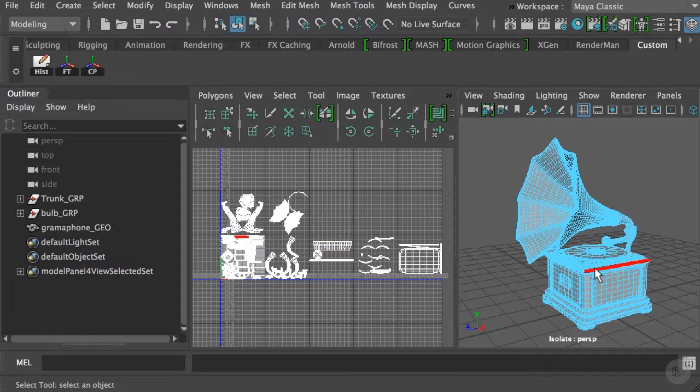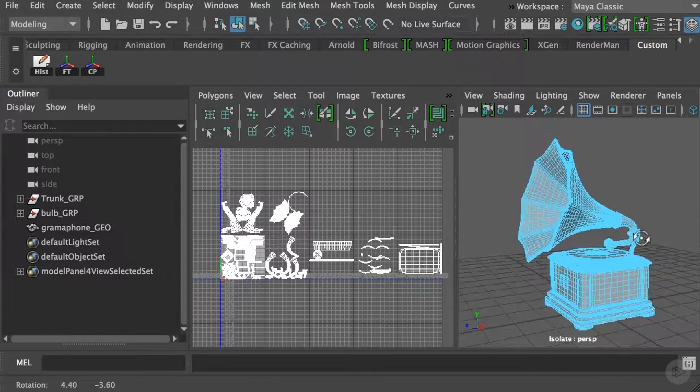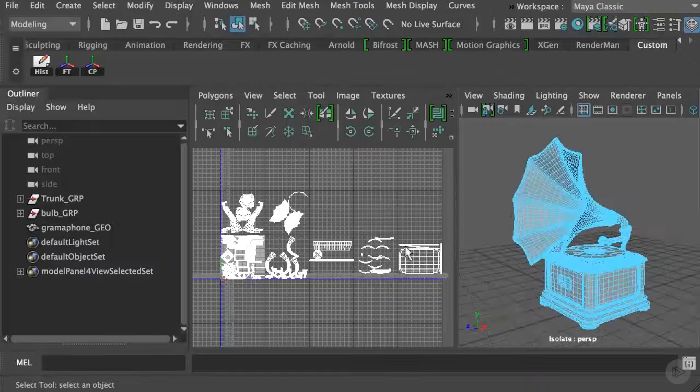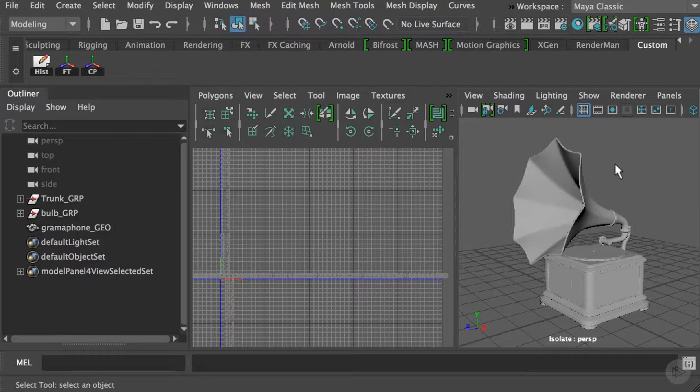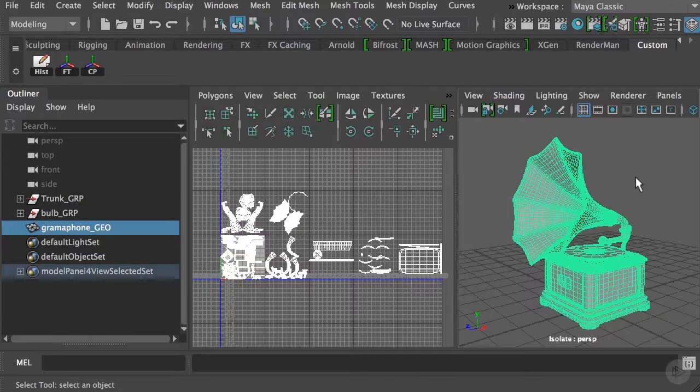So I try to keep every single part that has a different type of material in a different UV layout tile. This is because what we want to do is bring this as a UDIM object to Substance Painter and paint one singular texture, or set of textures depending on the channels, for each one of the materials of this object, but just apply one single material. So I will stop this here and continue with the course in the next clip.